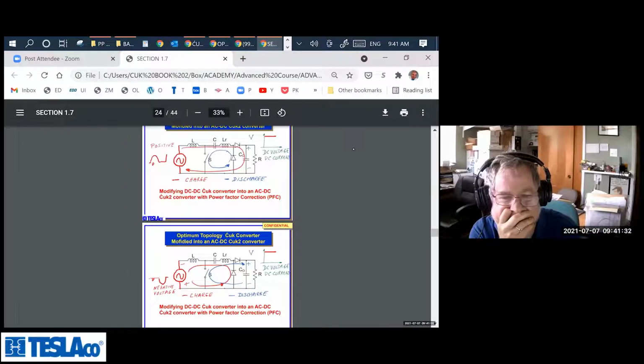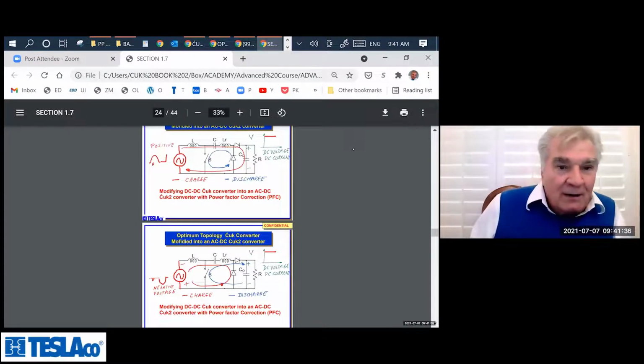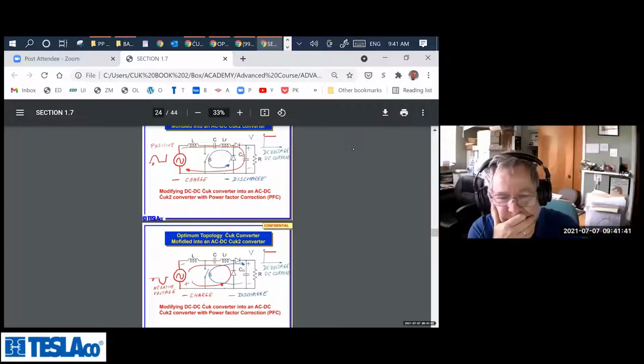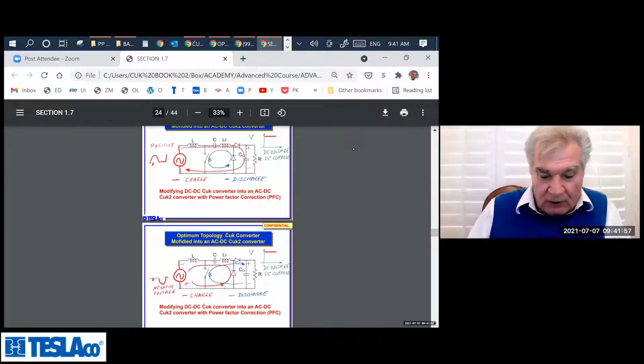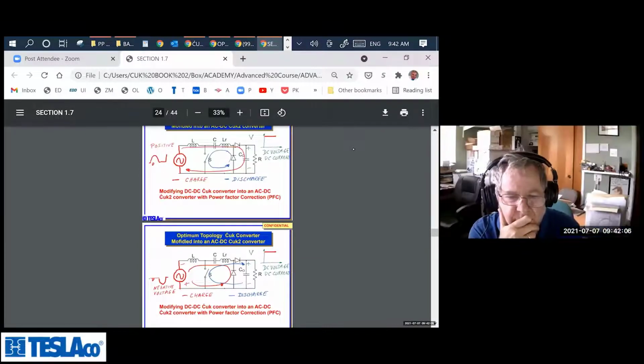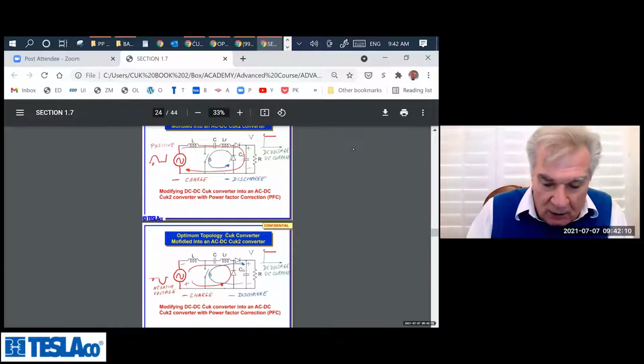Can you see that now these two diodes are doing what the full bridge is doing on input, right? Yep. So we don't need a full bridge input, it's a ghost. Of course, what is going to happen is in these two positions, when we are doing the charge positive cycle and the discharge, what is going to be the DC voltage on this capacitor? Anybody can tell me? What is the DC voltage on this capacitor? Which capacitor? C out or C? No, C. Oh, okay. I call it C and I call C zero the output.